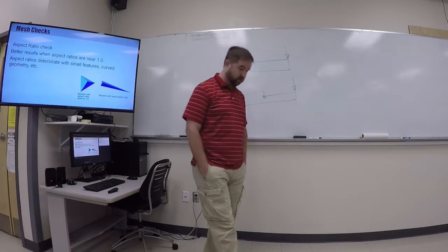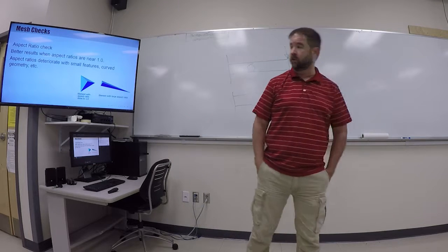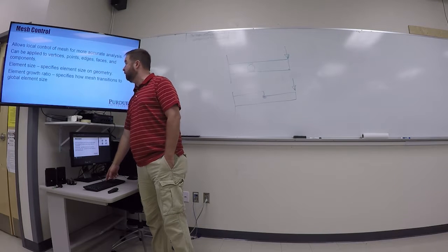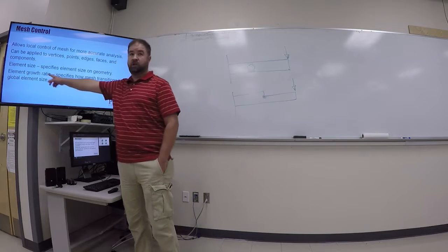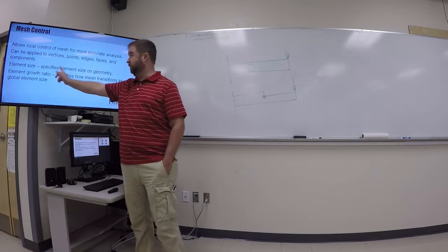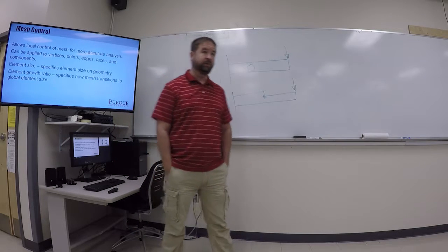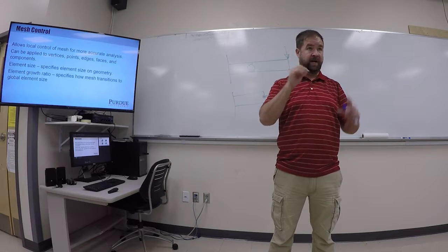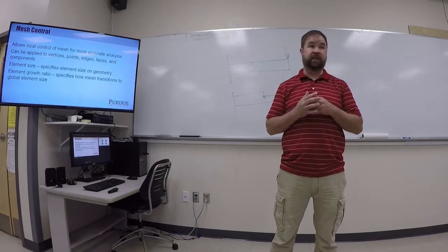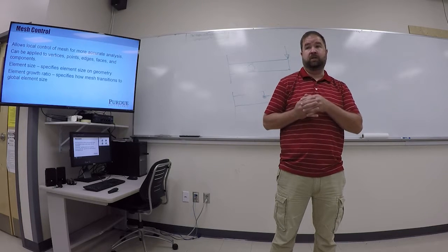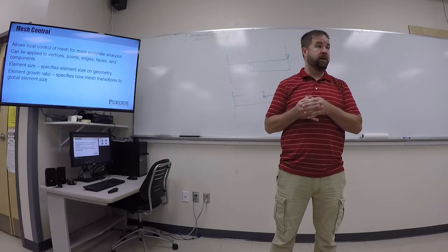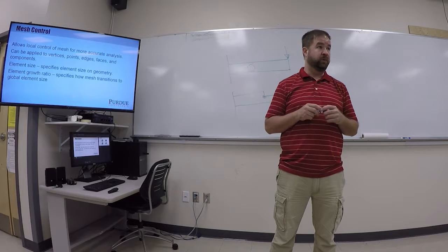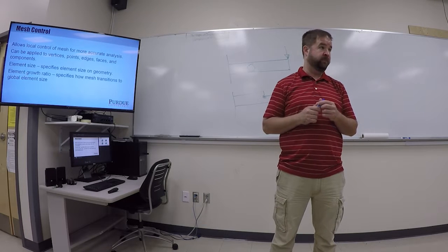So when you are setting your mesh control and setting up things like the element growth ratio, you can set it so that you get some really crazy, horrible looking elements by the way you change those values. And sometimes it'll kick it back out and say cannot mesh this because you've specified poor values for those changes in geometry.